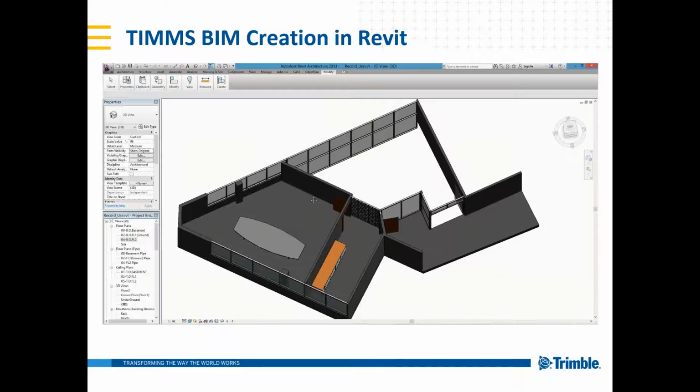available. Oh, here's a good question. Can you preload control points into the TIM so operators know where to look for them? Say if your survey crew goes through the building, airport facility prior to TIM scanning. Yes, absolutely. In fact, this is the normal operation. So you create a little text file that has control points and latitude, longitude, estimated accuracy. The operator is going to have to find the first one on the list because the cart doesn't know where it is. But after that, every point is going to be sorted by distance from the operator. So as he approaches a new point, it's going to be very easy for him to figure out which point from the list to select.